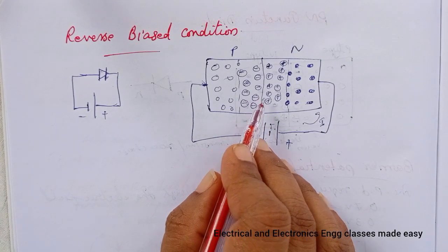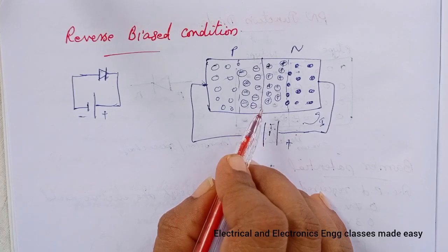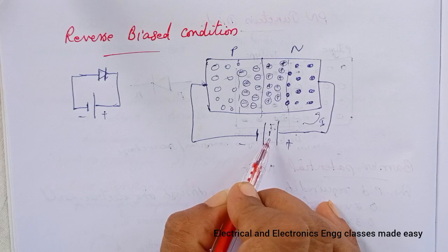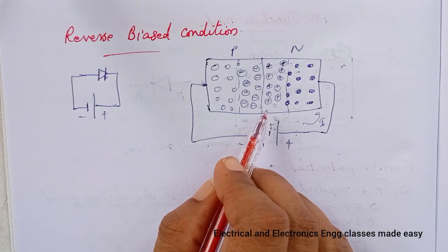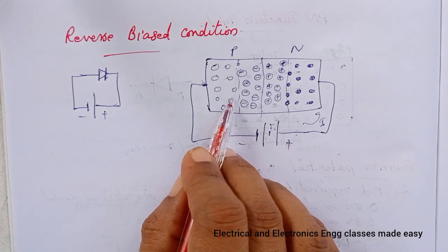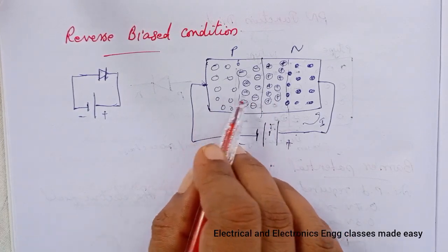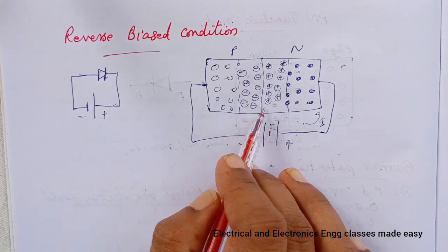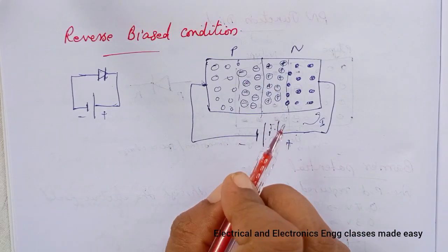The depletion layer stops growing when the difference of the potential equals the applied reverse voltage. And when this happens, the electrons and holes stop moving away from the junction due to increase in barrier potential and the resultant electric field.